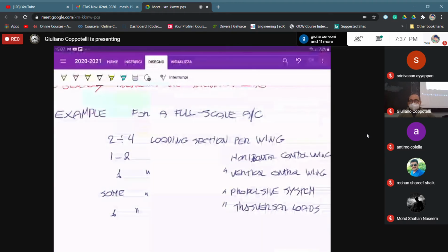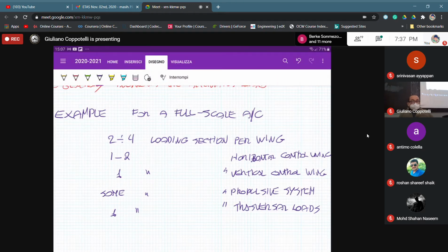We would like to have isostatic conditions. If you are having isostatic conditions, then we are very happy because there are no issues related to the possible yieldings that come from the modification of the constraint reaction because we are doing something. Okay, so we would like to have these isostatic conditions, but however, as you can figure out, that is not possible because the structure is there, and it's not said that we could have isostatic conditions when we are referring to a wing that is connected to a fuselage, for example, for our system.